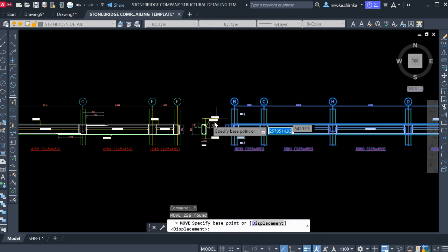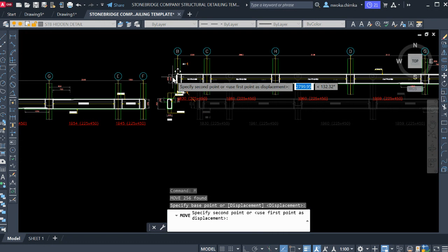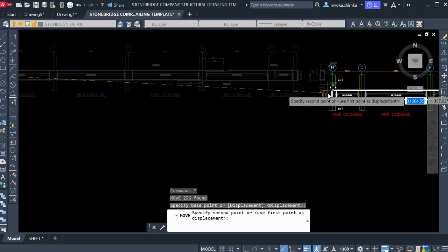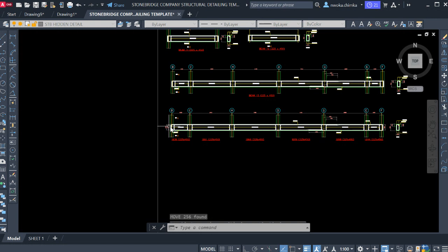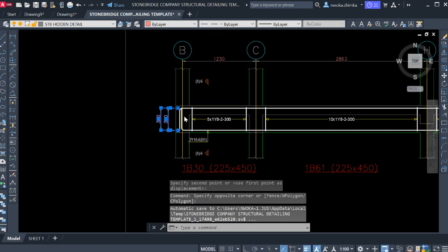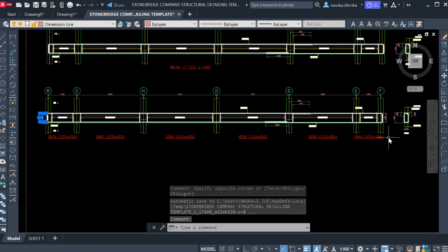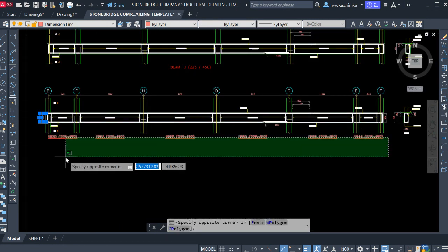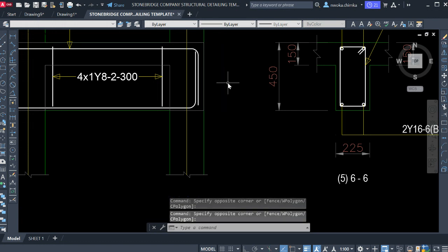Don't make that mistake of cutting another beam section. Always take the one that is directly with it, as you can see here. So we go right now to paste this here. This is our beam 14. Remove unnecessary things that came with this structural beam detail from Prota Structure, and remove this beam naming so that we can name it our own master beam name.